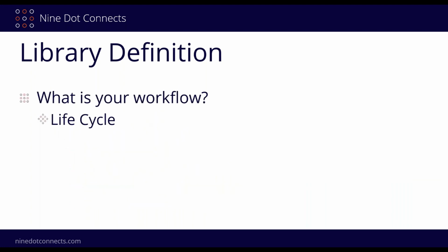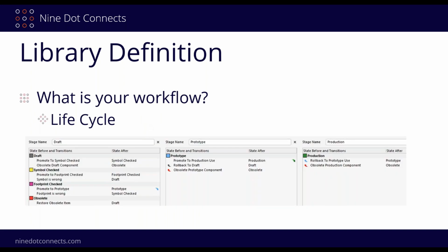Another one here is Lifecycle. Lifecycle to me is an interesting creature because I think we all want it, but there's implications to it. So what I did was I pulled this one out. This is an example that comes with Concord Pro or Altium 365, but you could also do the same thing in a database library. Instead of calling it Lifecycle, you could have a parameter that is called status. And Lifecycle is a really tricky parameter.